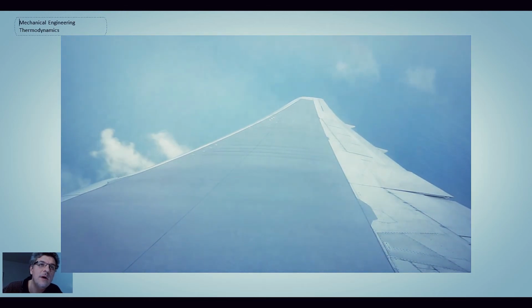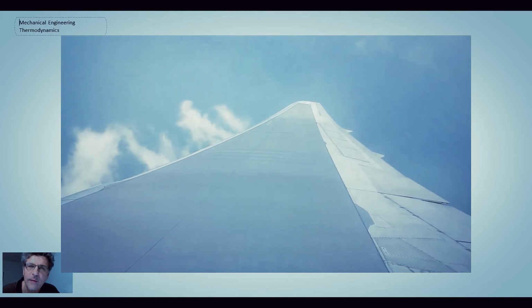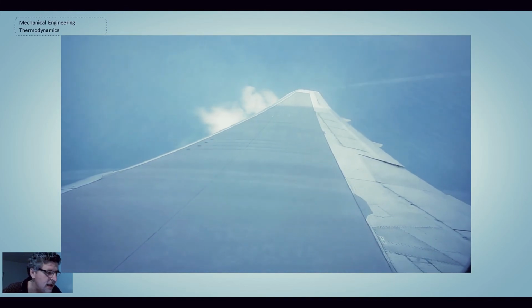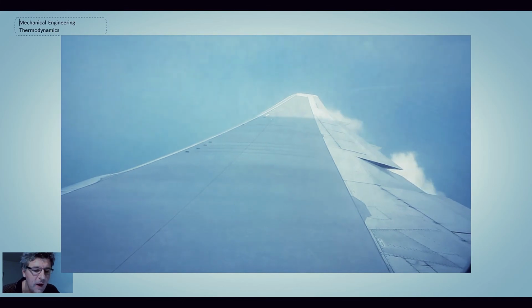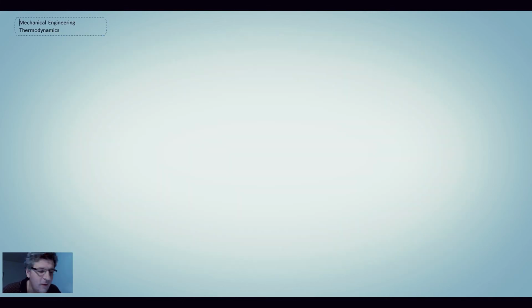And within that low pressure, you encounter conditions whereby you can actually get condensation coming out of the air due to that low pressure. So those are two different examples, one being frost formation on cars when things get cold, and another one is when you lower the pressure, you can actually start to see condensation, a similar sort of process. And you'll notice that the condensation appeared and then it went away with the wingtip. That's because the amount of humidity in the atmosphere will change as you're flying along, and consequently sometimes you see it and then it will disappear. You're going into drier air, and then you go into another region where you'll have moister air and you'll see the condensation start up again.